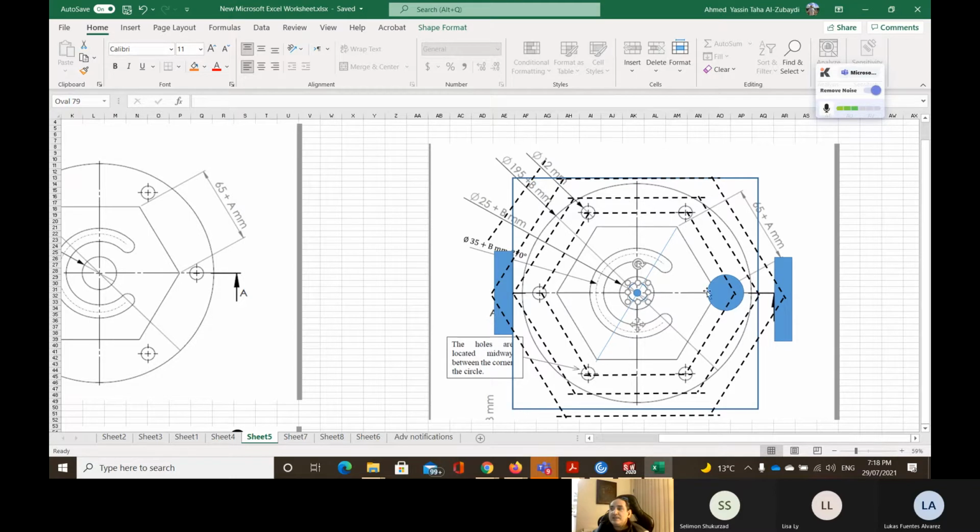And when we finish cleaning this one, we need to drill the holes. The holes are going to be point to point. That means G00 above that point, G01 to the maximum depth, G00 to Z equal to 5. Then we travel to the next point, and the next. So we do the drilling, go up, travel to the next one, do the drilling, and go up, until we finish all the holes.